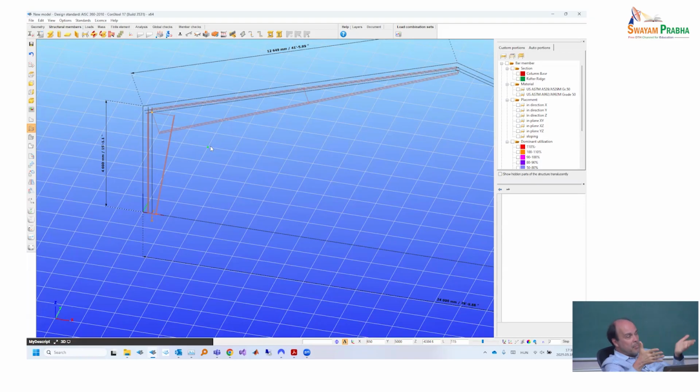Now, if we assume at this moment that you can satisfy the stiffness requirement of the AISC, and then you define a rotational and a point stiffness, a point support rigid enough, then for the calculation we can assume and model them as completely rigid lateral supports, okay? So at the moment we will assume that those are like that. Therefore, for all those positions where the purlin or the girth is attached to the rafter, we will assume a lateral out-of-plane point support to the external flange.